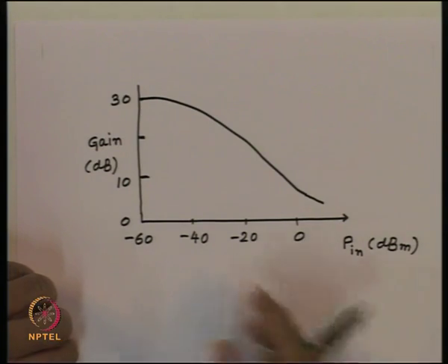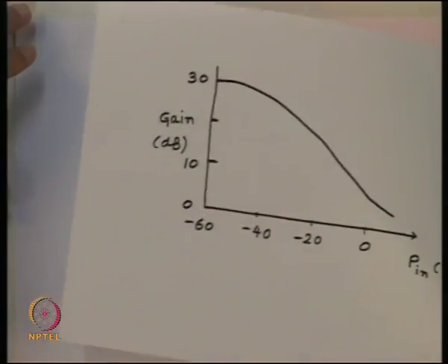So we can now write the equation for the powers of the signal and the pump, from the conservation of photons. There are a certain number of photons transported to give the population inversion. Out of this, the power is transferred to the signal photons. Power was first carried to the upper level, and then extracted from this system in the amplified signal photon.